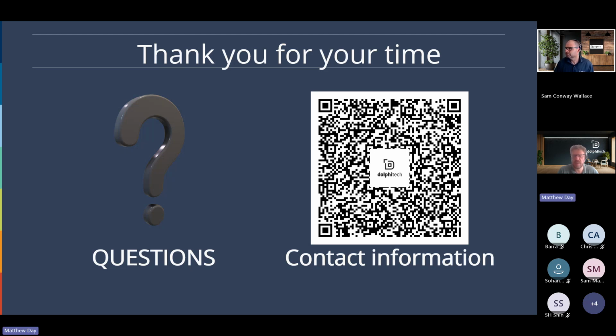Yeah, that's a really good point. We've talked about it before in other webinars, videos and demonstrations, that the Dolphicam 2 software saves all the data within the range. So if your part is 5 millimeters thick, but your range is set to 25 millimeters, you're going to be saving data from a lot of dead space. So efficiency in the setup is key as well.